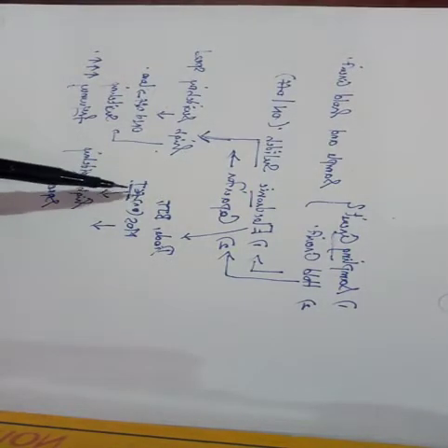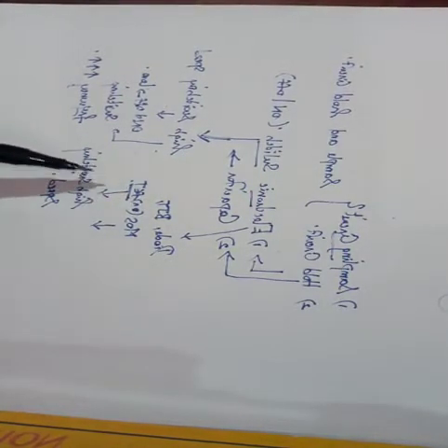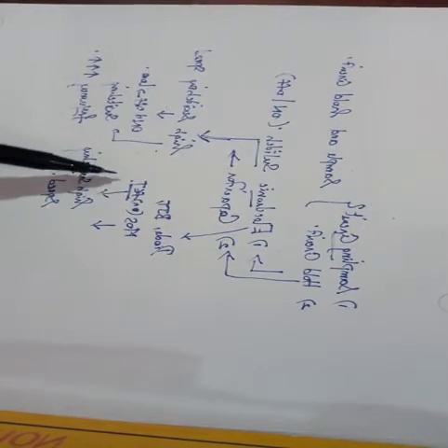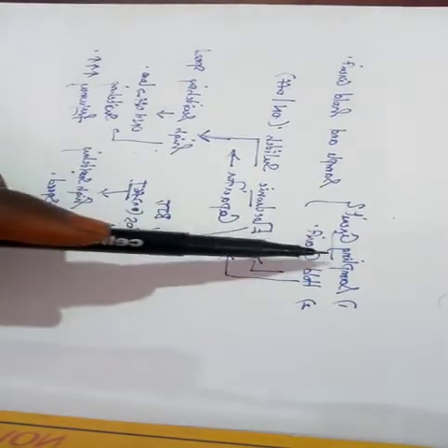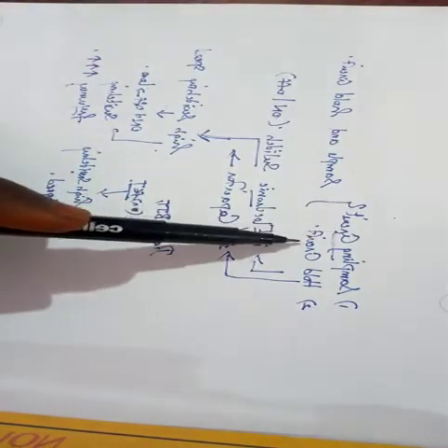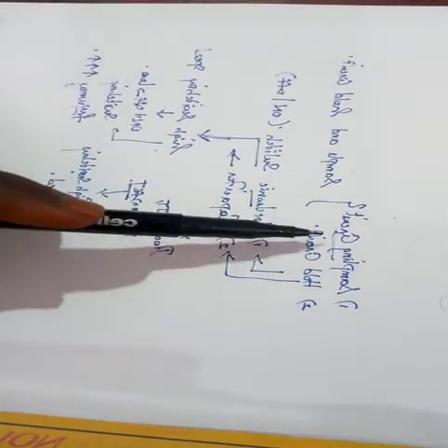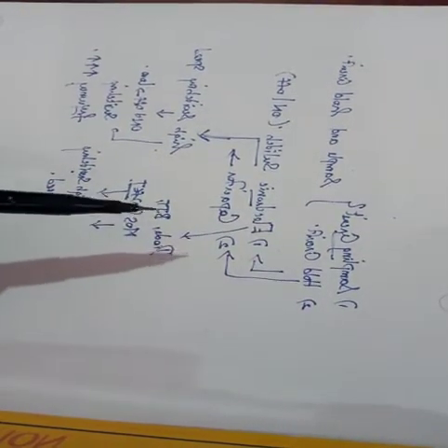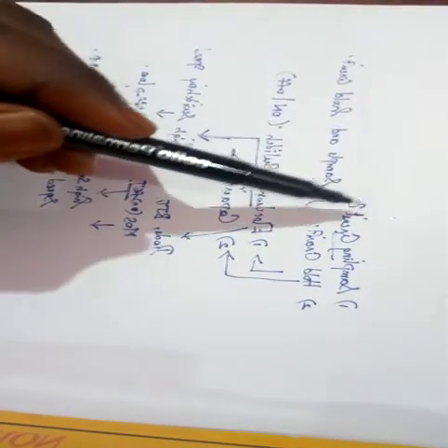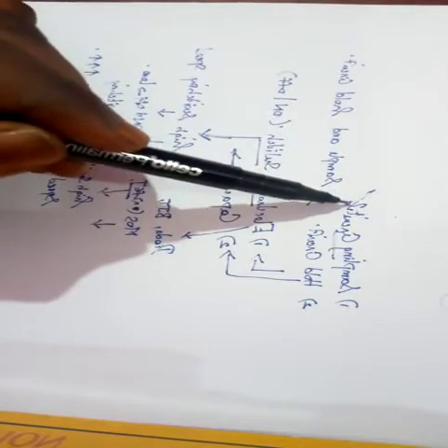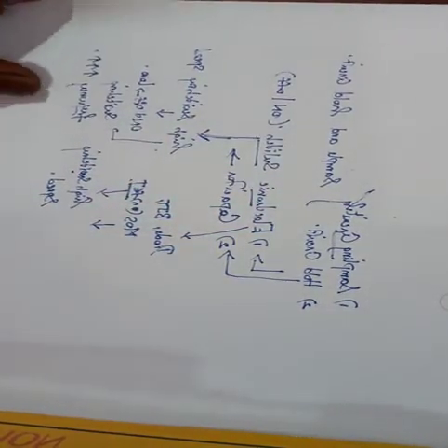So choosing a high switching speed switch, it is preferable to use a FET switch to accomplish the sampling operation. And you can use a capacitor for charging and discharging the analog value or the analog signal. So let me see how it works. First we will discuss the sampling circuit, which is accomplished by a component called an electronic switch.